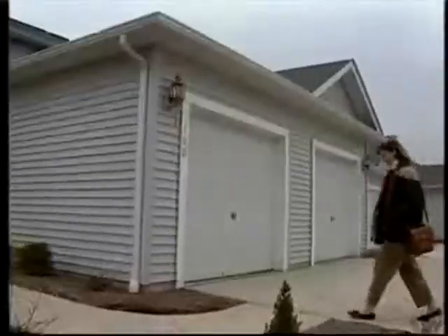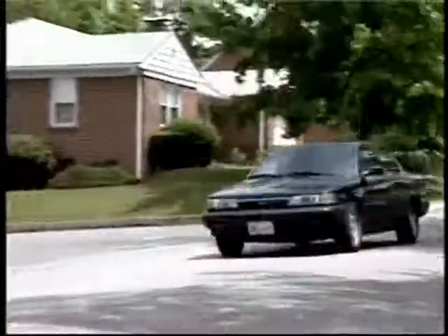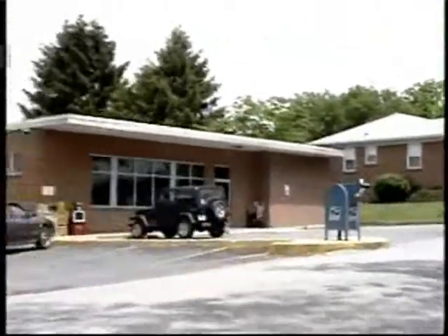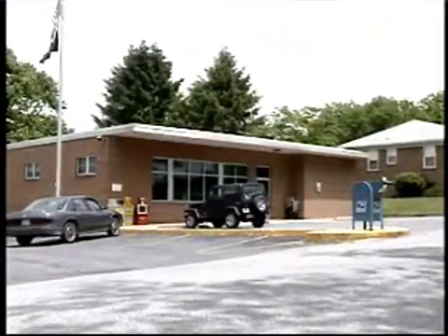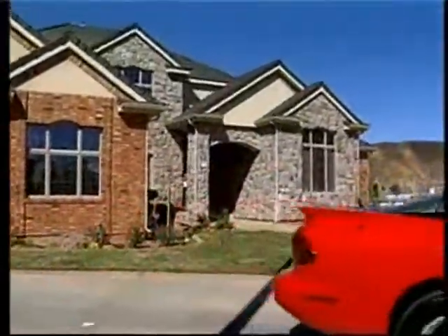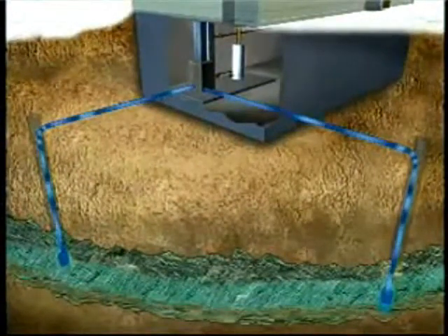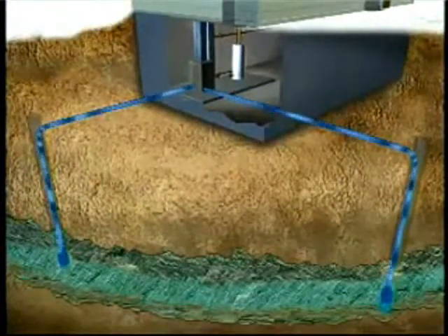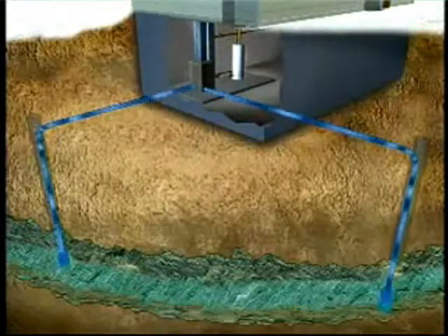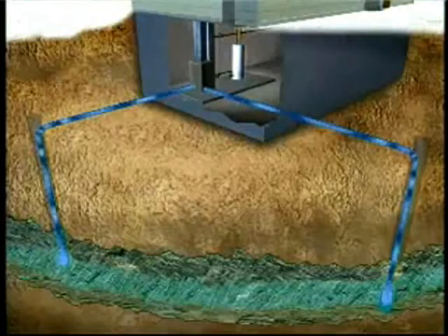Since it's not necessary for the heat exchanger to be connected to the rest of the system above ground, whichever type is installed can be placed within existing landscaping, under sidewalks, driveways, and parking lots, or even beneath the building itself. In an open-loop system, on the other hand, groundwater from an aquifer is pumped through one well and passes through the heat pump where heat is added to or extracted from it. The water is then discharged back to an aquifer or harnessed for other water management uses.